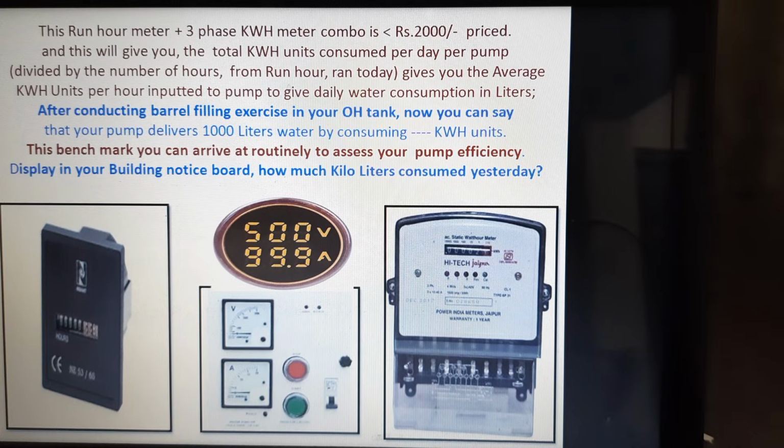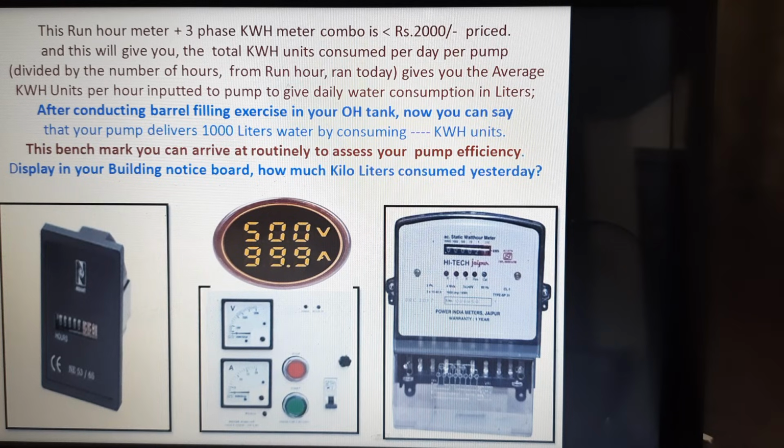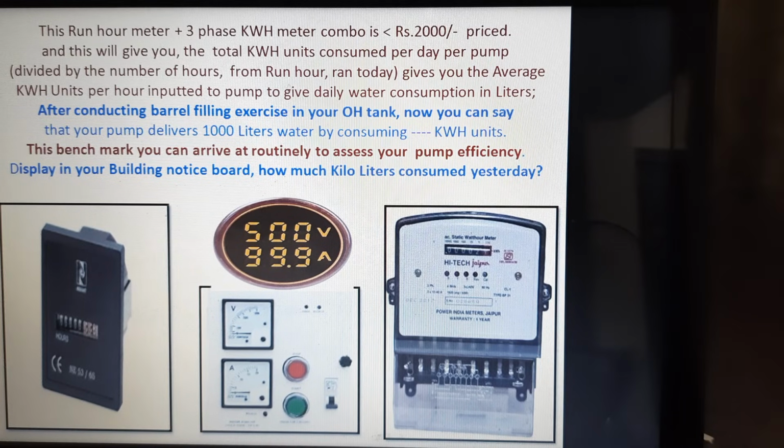normally to see how much water can be filled in a bucket at the delivery of the pump, at the overhead tank or at the sump, and how much it is delivered. You measure it by using the bucket filling exercise. Normally it is done in energy audits, and in building energy audits it can be done as such. It can be done at the overhead tank, where the pump delivers.